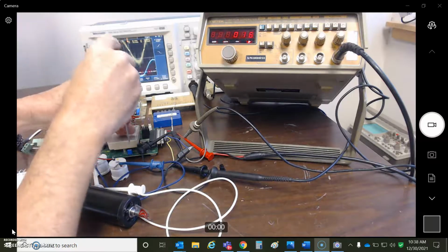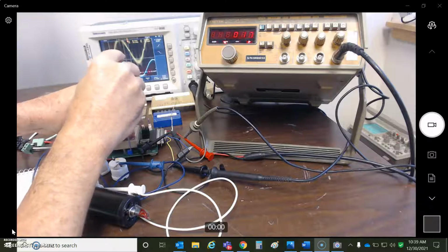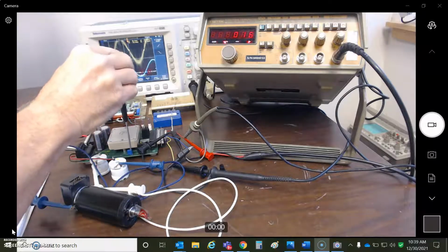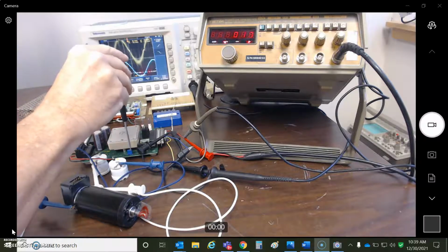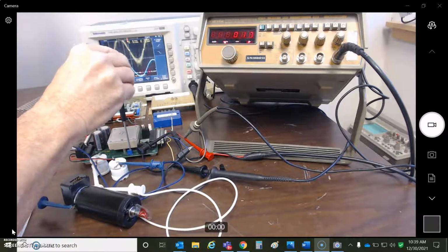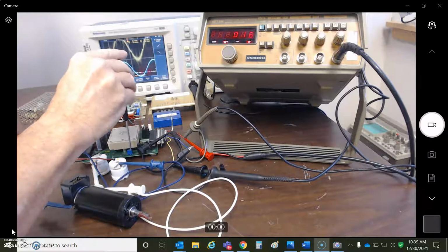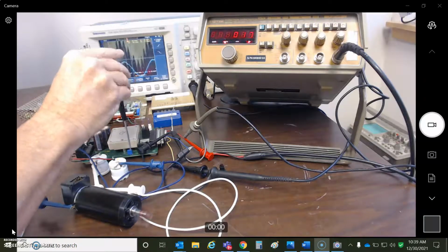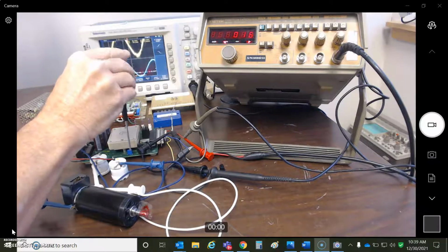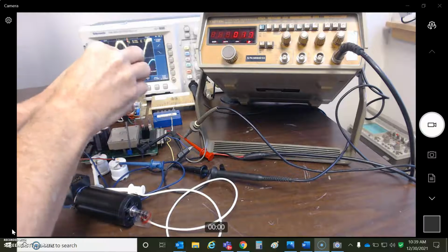But the reason I'm doing this test is to help show the benefit of the Bantam versus some of the older drives. I can adjust the offset, and I can get creep one way or creep the other. So this is current, a small amount of current applied to the motor. If you have too much offset, the motor starts to spin, and eventually it just runs away. Okay, so runaway in a current mode is not good, so you got to stay away from runaway. And then, of course, you can get runaway in the other direction.